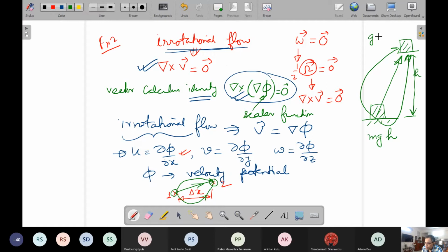Similarly, when we say that we have irrotational flow, what we are meaning is that there is a conservative field that is describing the velocity, and therefore conceptually we are expecting that there is no dissipation. See, if you have different paths, but the concept doesn't depend on the path, what it means is that different paths will give, in terms of say a very common school level physical understanding, different friction. So what it means is that therefore we are talking about a concept where friction doesn't matter, and for fluid, friction is synonymous to viscous effect or viscosity.